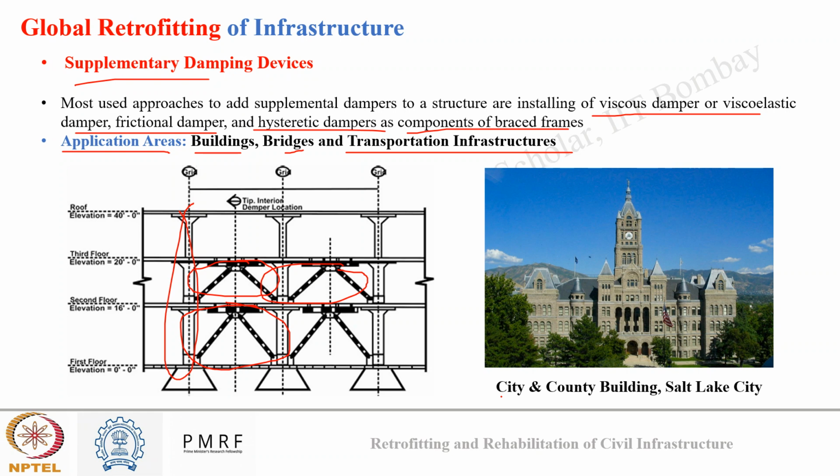If you remember, in the last session we had a very brief, detailed discussion of this building, how for different floors some seismic measures were taken. Those seismic measures were nothing but supplementary damping devices, and near the foundation, by scraping the joining between the footing, how around 400 base isolators were installed in this building.